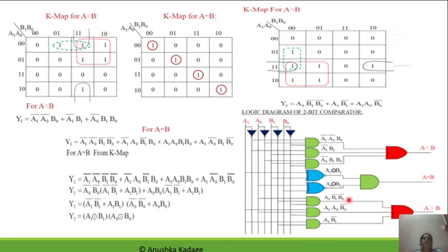One is the identity comparator with only one output set as 1 or 0 based on the equality condition of the presented 1-bit numbers. Then we have gone for the 2-bit comparator. Based on the truth table of the 2-bit comparator, we have obtained the simplified circuit.